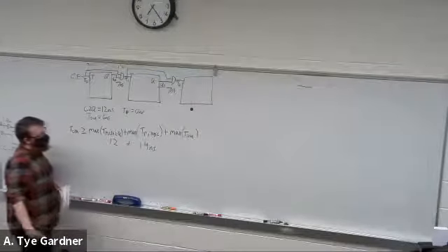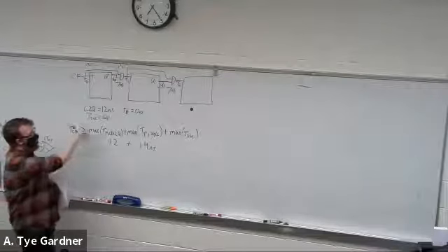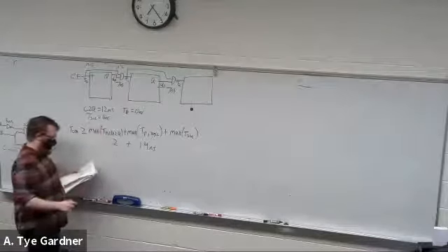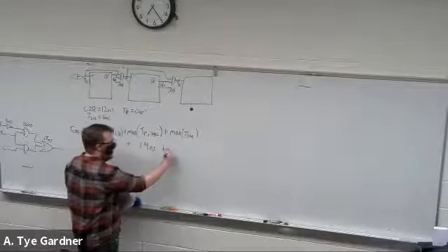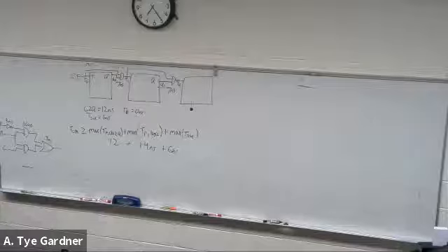And then my last one is setup time, 6 nanoseconds. That's all. So this one doesn't have feedback, but it still has this kind of critical path. It all follows the same kind of thing, that we need to make sure that we have set up that last one in time before we start counting.